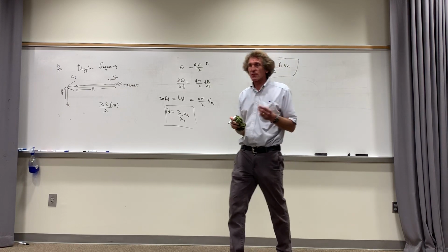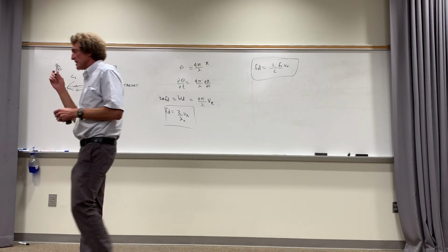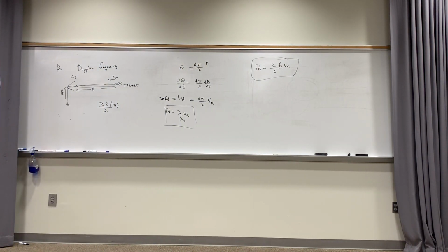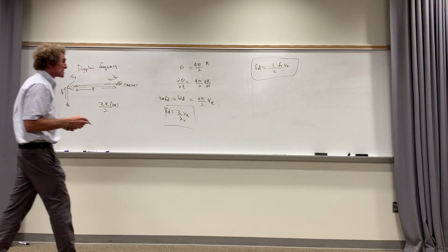Now, how Doppler shift works is this. If I'm transmitting a 10 gigahertz signal, and I calculate a Doppler shift of 100 megahertz, if the thing's coming at me, it increases the frequency. So it would be 10 gigahertz plus 100 megahertz that I'm actually receiving. If it's leaving me, then it's going to be 10 gigahertz minus 100 megahertz. Follow me on that, everyone? So you have to remember that. It's either going to be an increase or a decrease in the actual frequency.